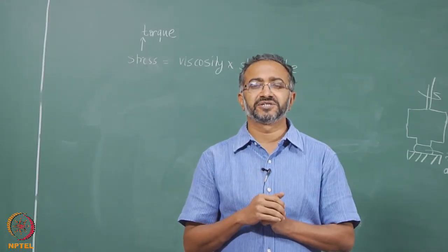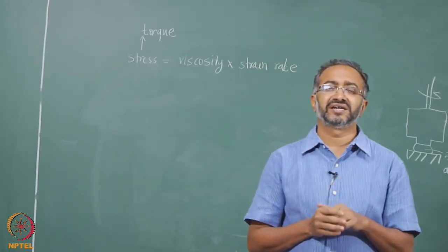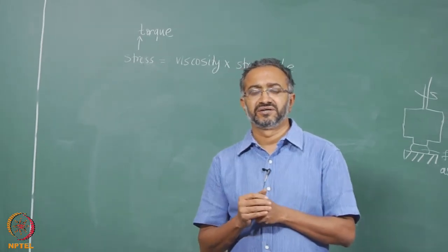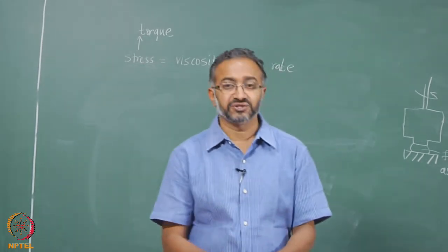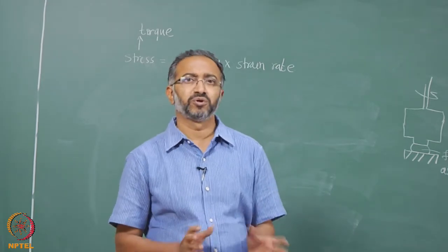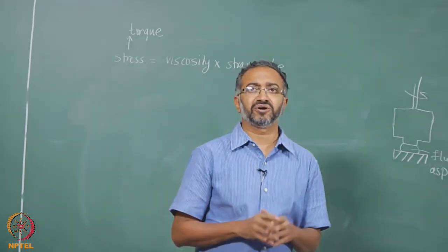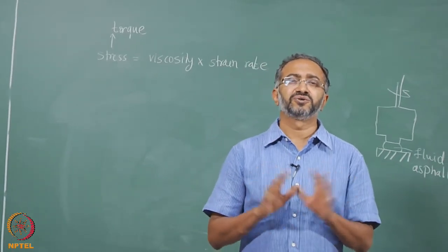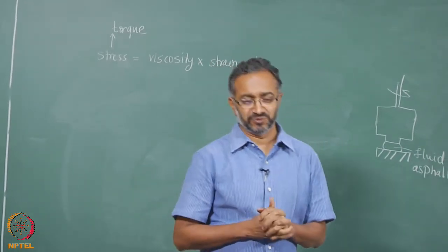But one thing which you should remember is, in the end, the ability of an instrument to do viscoelastic measurement depends on how accurately it's capturing torque and how accurately it's capturing rotation. And this test on Newtonian fluids does both of that. It tests for torque, it tests for rotation. So therefore, we continue to use silicon oils as standard oils most of the time.